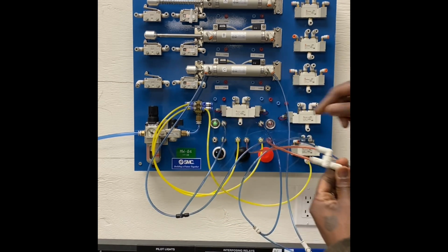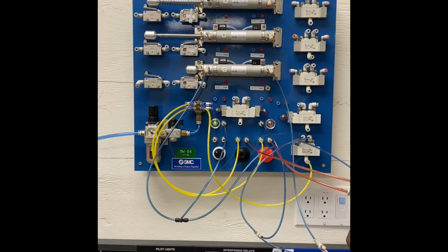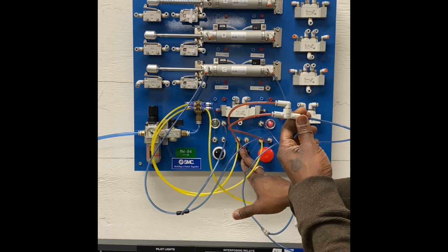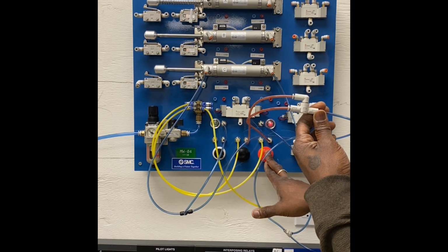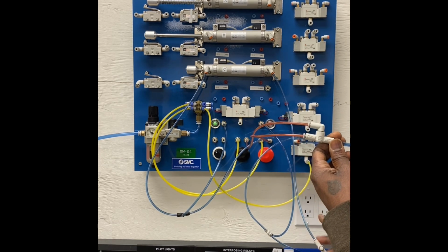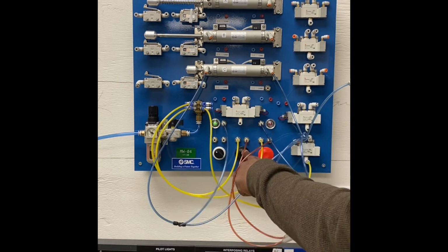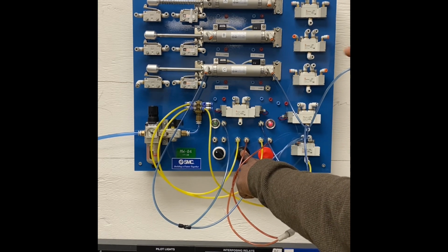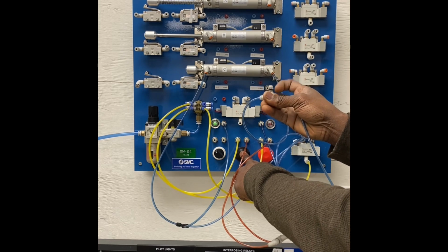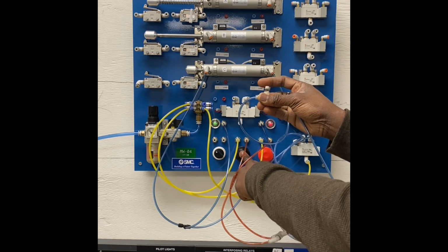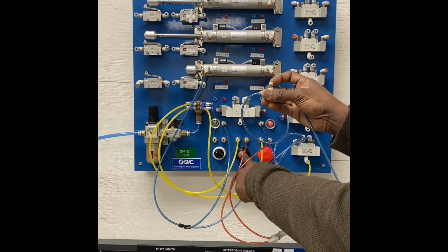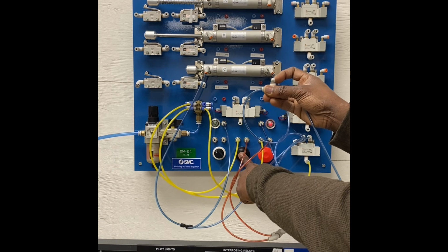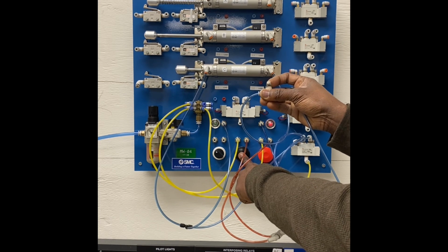Well, what we mean is that we will be controlling the amount of air, reducing the amount of air getting into the cap end of the cylinder, causing the rod to extend more slowly, dependent on the position of our needle valve on the flow control valve. You can see the rate of stroke changes as the needle position changes on the flow control valve.